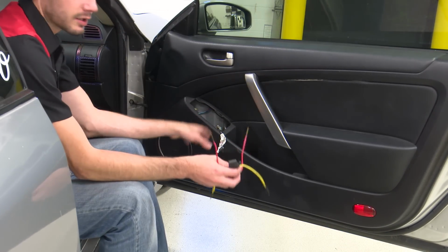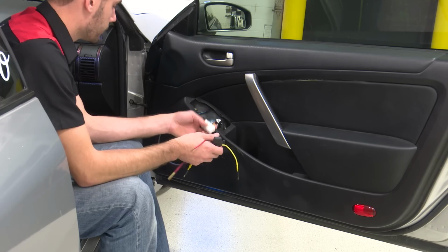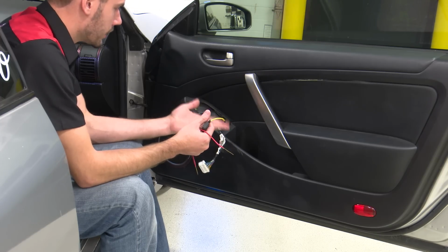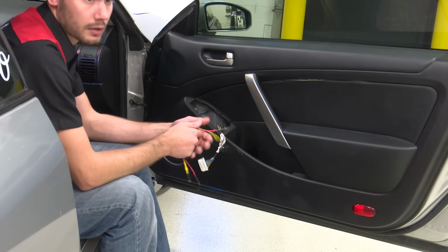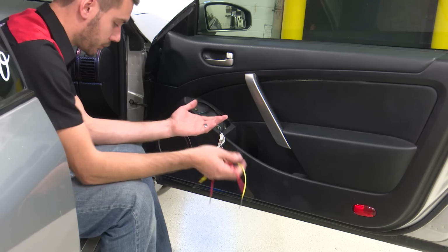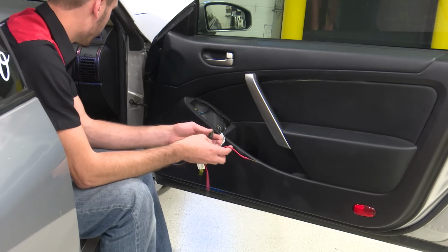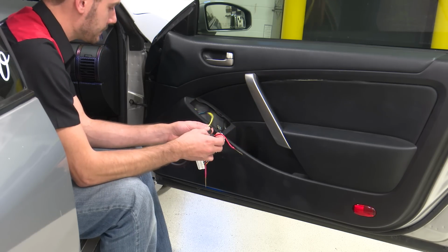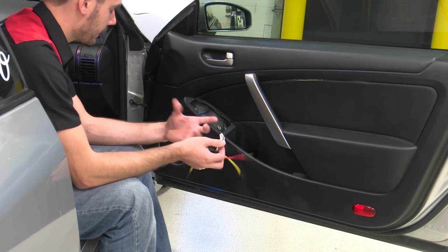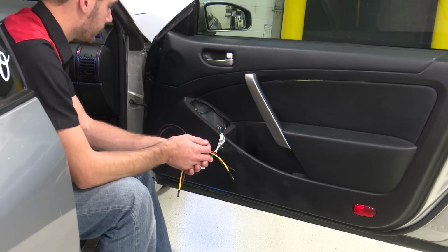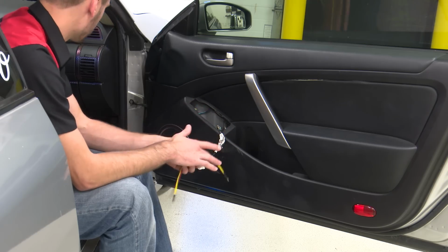So now this is not an intermittent problem, this is a consistent problem. We know that we have power and ground being fed to this switch. We know that our motor is functioning. It's time for a switch, right? I mean, a couple quick tests. There are a few other things that could possibly be an issue, but it really looks like we have a switch problem, right? We have no control over this side. We have power and ground, and our motor is functioning.